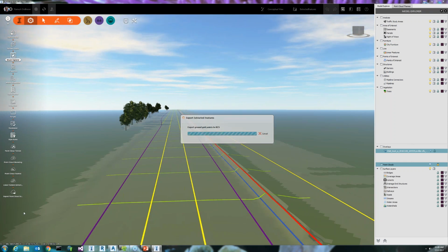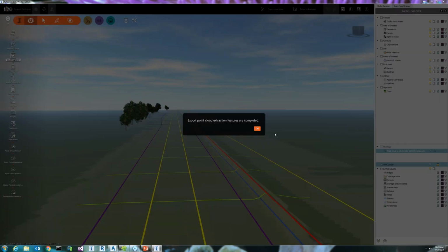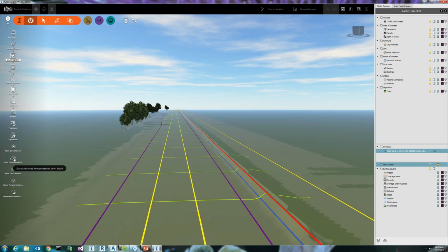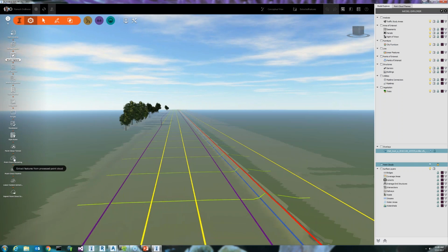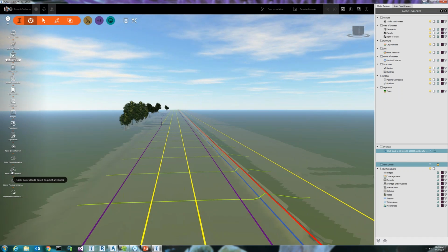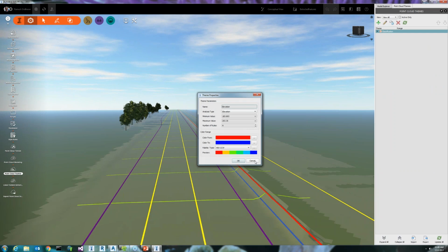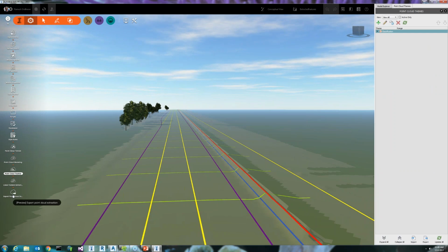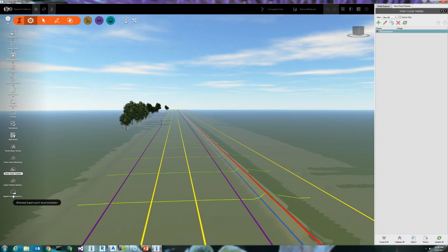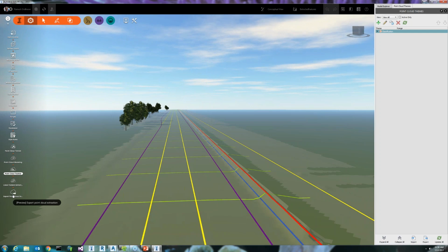So now this export is the last piece in my list. So now you know how to bring in the point cloud data, run the step number 1 point cloud terrain, and use the linear features for the breakline extraction, the point cloud modeling for any point features or GIS features you want to extract, or extopo features for design. You can use point cloud theme to view the point clouds better. I just covered only the classification theme, but there are a lot more themes you can customize, you can do much better. And of course at the end you can export it and take it into your design environment also. So now you can complete the whole workflow and do your road design or anything else much easier with the reality capture data. Any questions, Eric?